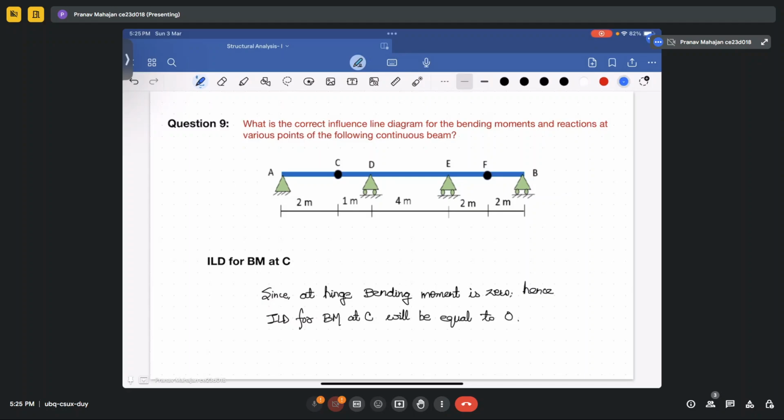Okay, so in this session, we have covered all the concepts related to influence line diagram and how we can determine the values of shear force and bending moment pertaining to the moving load along the length of the beam, whether it is point load, UDL load, and sometimes it can be non-uniform point loads, and how it is affecting the structure.